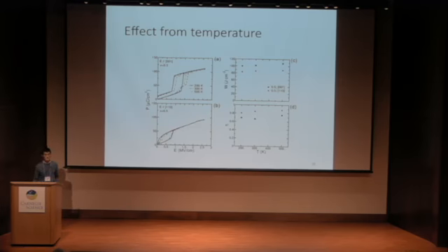Actually, I have a quick comment. I'm an experimentalist. I worked with bismuth ferrite for quite a while, 5 to 6 years. I know it's a very tough animal to deal with, especially the leakage current. So such a high electric field, something like 6.5 megavolts per centimeter, I'm not sure you can achieve. Even though you can achieve it in really thin films, I'm not sure it will be useful for any real applications because the energy is so low, right? So from a practical point of view, thick films may be more meaningful. If you have a little bit lower energy, but you have more juice to use, that may be more useful. Just my own comment.